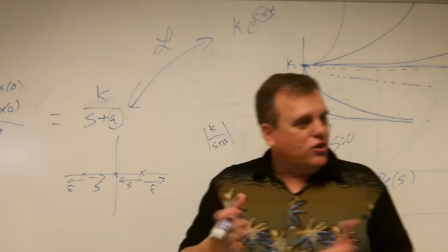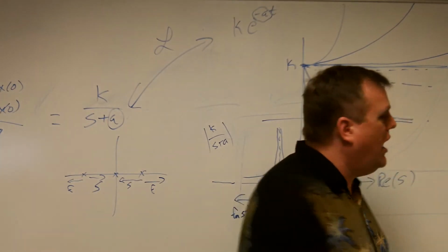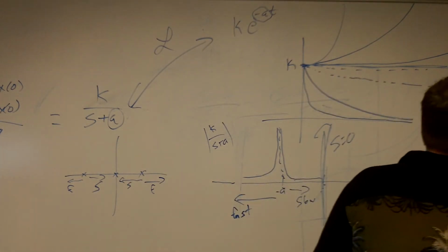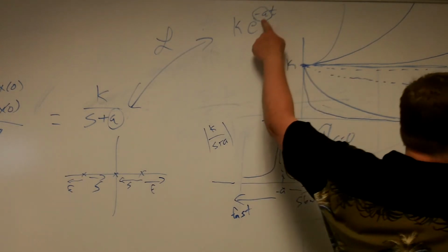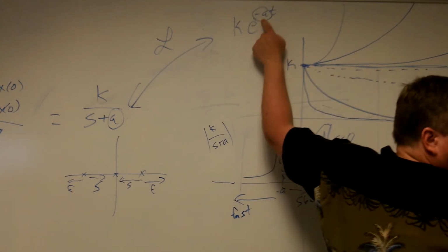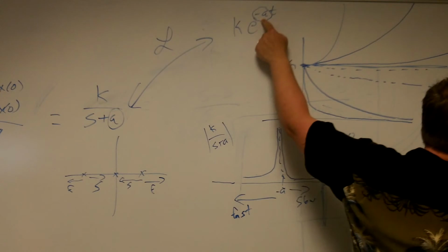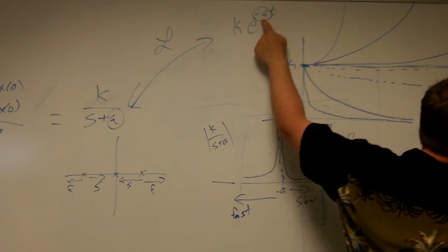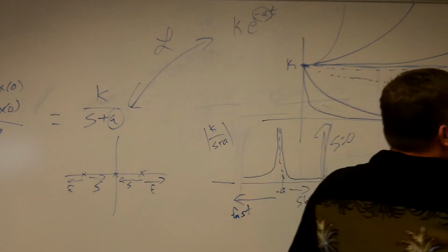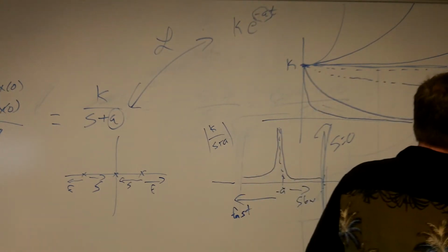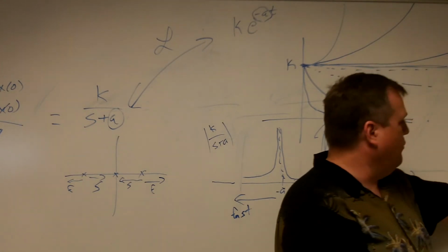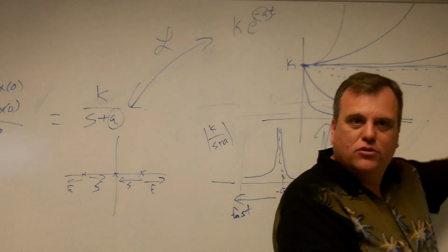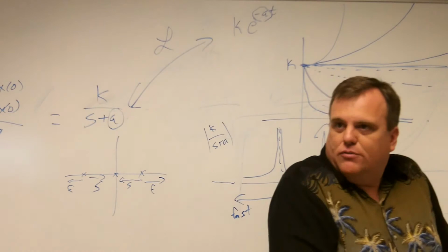So if you have a particular make-it-go-away response, inside the S domain I just say, hey look, in order to achieve that, I need an A value that's at least some minimum amount, say A sub 0. So this is the stable area. I don't want to go in here, that's too slow. You just got to move all your poles left of that line that covers your minimum time.